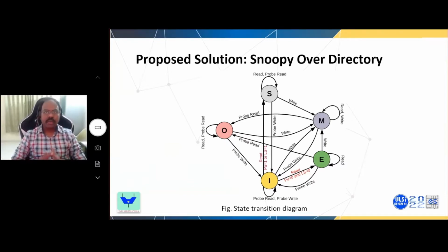And in the L2 cache, the block is verified in the directory entries. If the block is present, and if the block is shared only within the chiplet, a simple directory lookup is made, and the corresponding owner of the block responds with the data to the requesting cache, which is very similar to existing protocols, and no changes to the directory entry except for the updating of the sharer vector are required. It operates similarly to any conventional directory protocol.